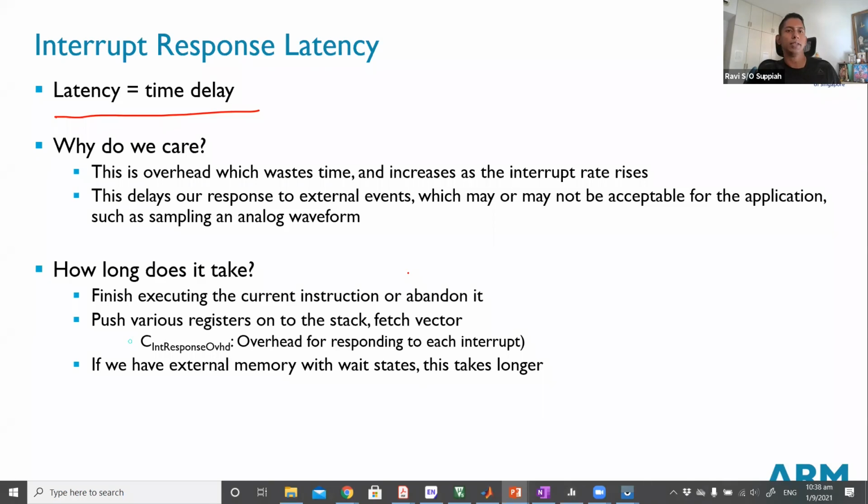So in situations where your hardware may be triggering the interrupt very frequently, then you need to rethink your strategy. Because if you have an interrupt that is always triggering, then you waste a lot of time just trying to service the interrupt, and then the main program never gets a chance to run.